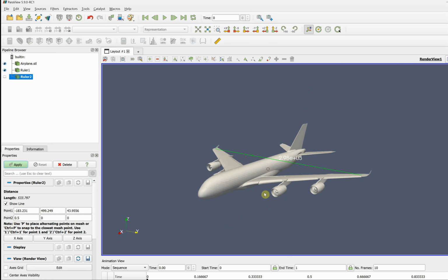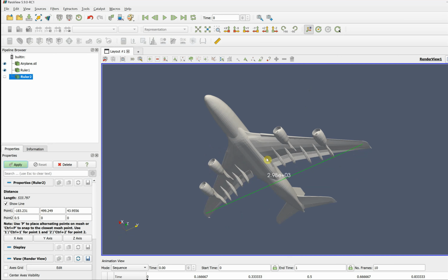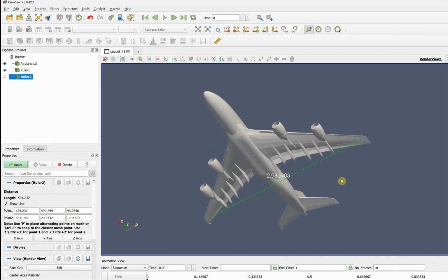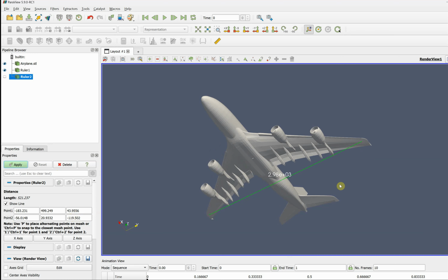And the last thing we want to get is how far above the ground this is. So I'll click on this point and get that. And the Z location looks like it's, if it's centimeters, it's -1 meter. So it'll have to be raised. And those are parameters that you have to keep in mind when running the C3d GUI.